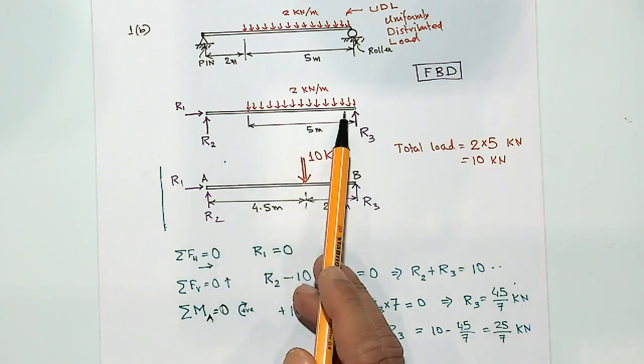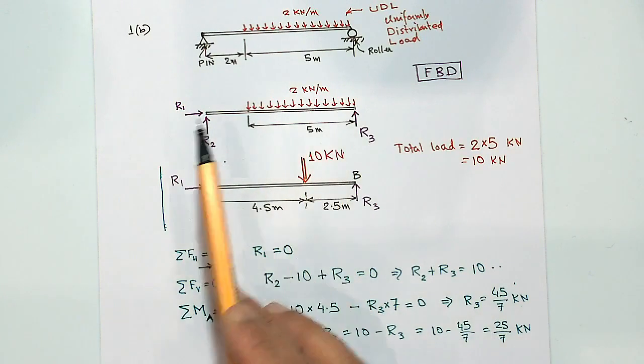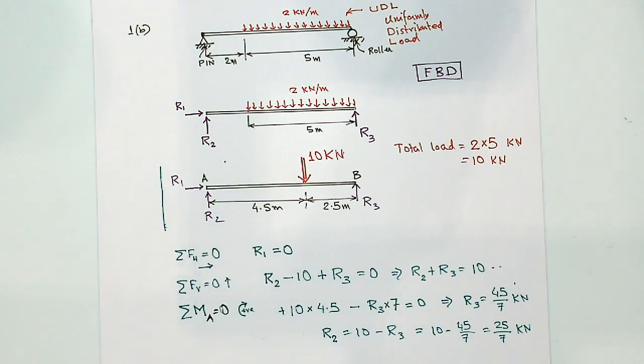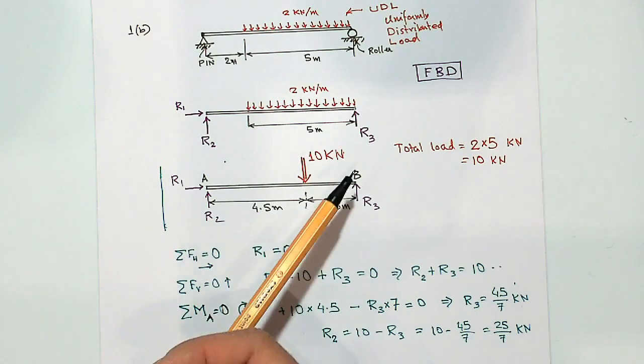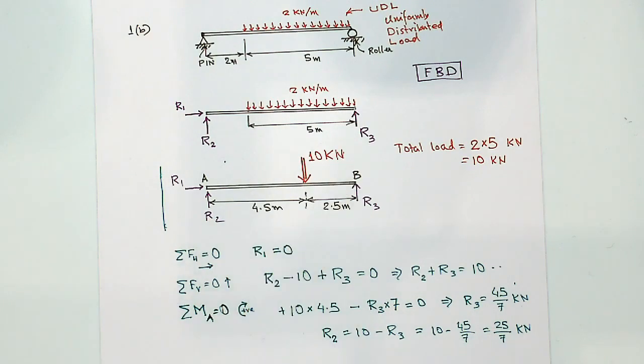Yes, most of the forces or load are on the right hand side of the beam. So R3 would have a larger share of the load, which makes sense in here. So develop this sense check whenever you do the calculation. Don't always believe what you get from the calculator, because you may have mistakes with your calculations there.